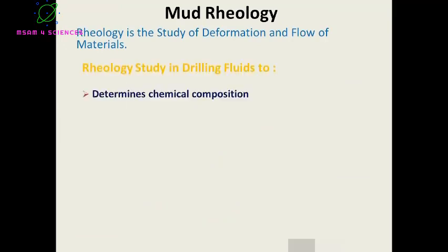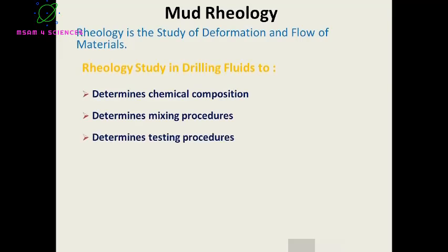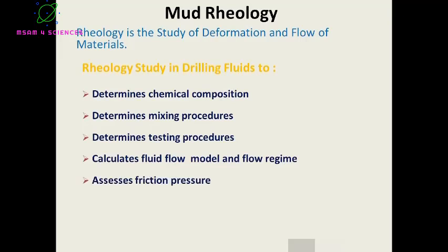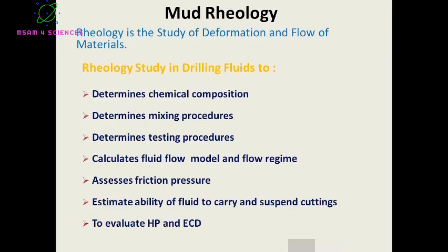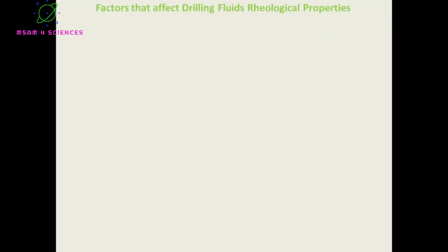We need to study rheology in drilling fluids for many reasons or purposes. First, to determine chemical composition, mixing procedure, and testing procedures; calculate the fluid flow model and fluid flow regimes; assess friction pressure; and estimate the ability of a fluid to carry and suspend cuttings. Finally, to evaluate hydrostatic pressure and the equivalent circulation density.